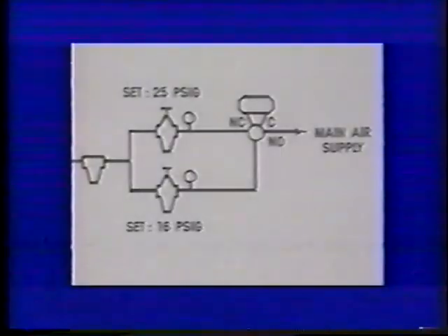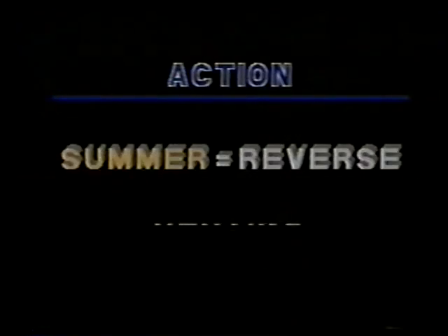datasheet. Now, let's take a look at the summer-winter changeover thermostat. Like the day-night thermostat, the summer-winter model utilizes a dual-pressure main air system. The summer-winter thermostat uses the dual air pressure system for a seasonal changeover of cooling and heating functions.